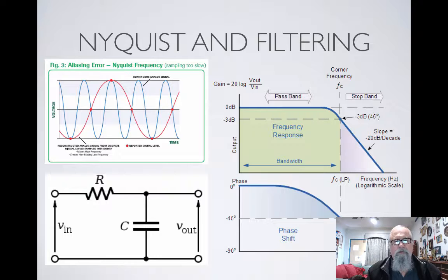And in this, the simple example I've got here is probably the most common, which is low pass filtering, where we put an upper limit on the frequency component that we will accept into the system. When filtering, we have two components. We have our pass band, this is the signal that we will allow through, and we have a stop band. So again, in the case of a speech signal, we would limit our signal at 3600 Hertz, and anything above 3600 Hertz, ideally, would be blocked from getting into the system.